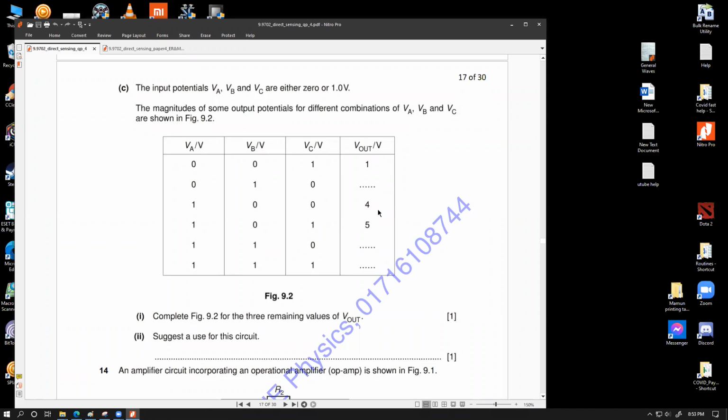An ADC circuit has to have the capability to convert a certain given voltage into bits, which would ultimately mean the equivalent decimal number in binary. Now, if we had a certain circuit which could convert, let's say, 5 volts into 101, you have to have 3 different outputs. So your first bit MSB, then your middle bit, then your LSB. So if you have those bits produced from a single input voltage and they were relevant in terms of the binary digital conversion, then yes.